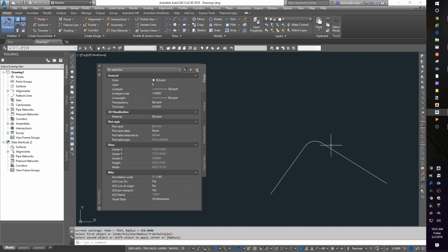What we used to do in the old days is we would actually fillet items with a radius of 0, and then we could put in a circle tangent radius, circle TTR, and I can say tangent to here with a radius of 250, and you basically did the same thing, except I need to trim. Fillet was quicker. Okay.